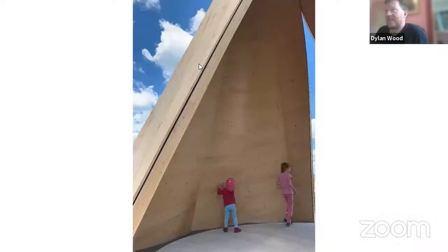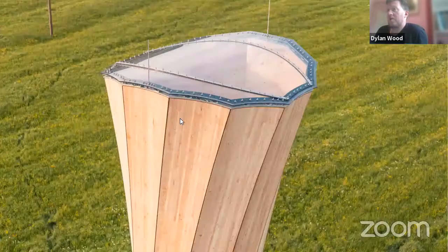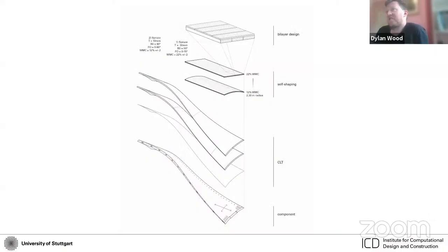I can answer, I guess, more specifically about the tower. Because it is a natural material, there is always some variation within many of the boards. But the types of parameters that we control are actually shown here. It's maybe a little bit small, but the main thing is the moisture content that the wood starts with in the active layer. In the case of the tower, the wood was almost freshly harvested from the trees, so it has a really high moisture because it's going from being basically living tissue to building material. It's in a transition.